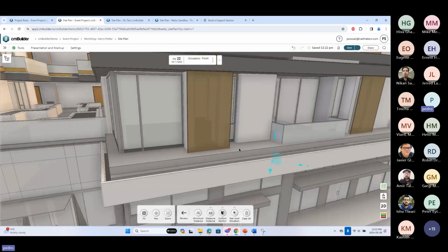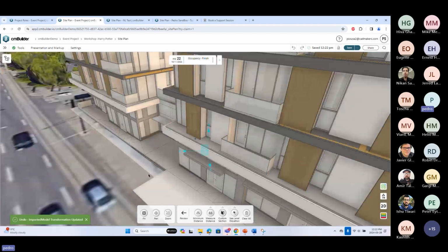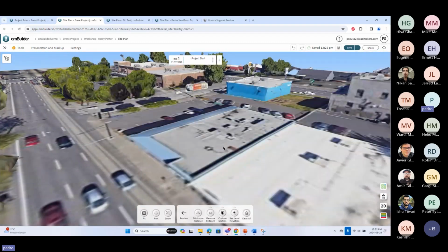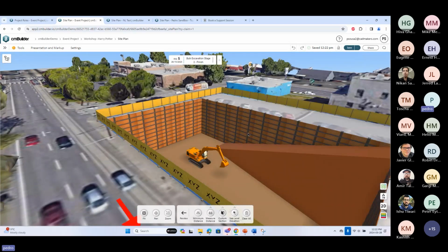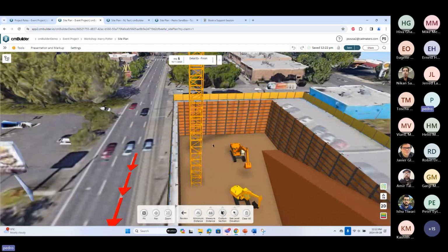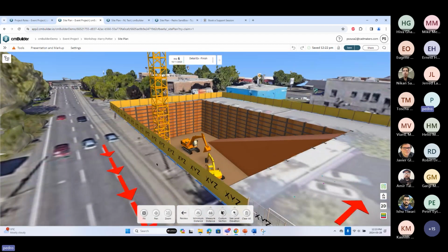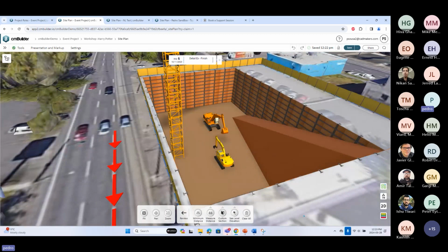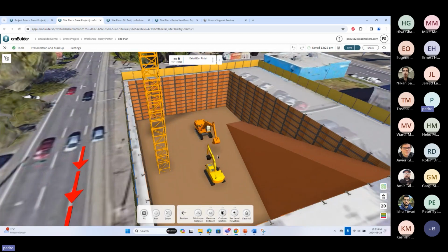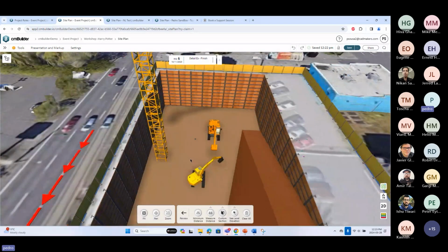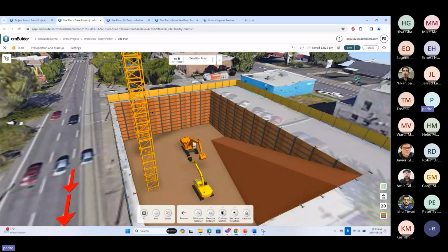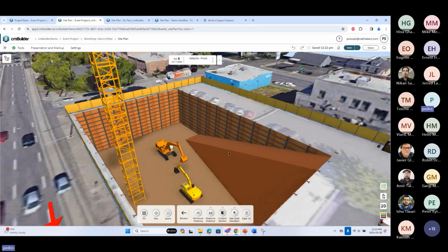So this is a good way for you to work with absolute references, but keep in mind that if you're working with absolute references, like positioning your model exactly where it's supposed to be on the sea level elevation, you should always check your terrain around that area, because the terrain that is created by default is coming from a satellite scan. It might not be accurate enough to fit the actual 3D model. So it's a good practice to always check these elevations on your terrain if you're working with absolute references.